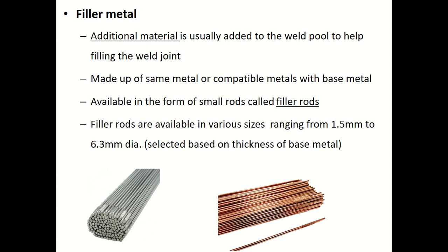It is available in the form of small rods, which are called filler rods. You can see some aluminum filler rods and copper filler rods shown below. The filler rods are available in various sizes ranging from 1.5 millimeter to 6.3 millimeter in diameter, and this is selected based on the thickness of the base metal.